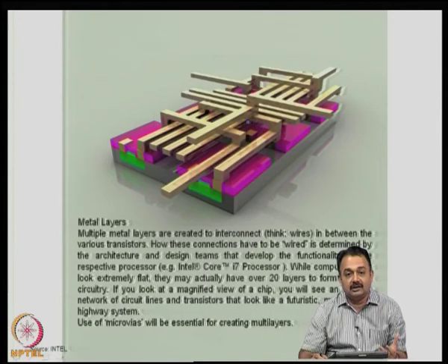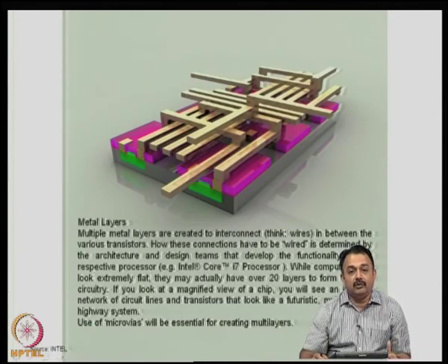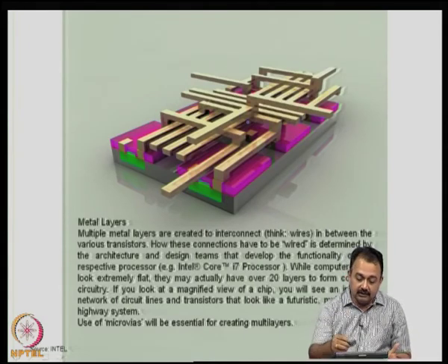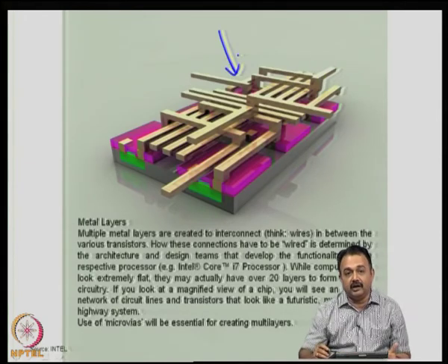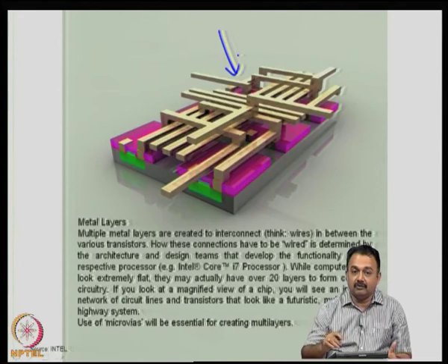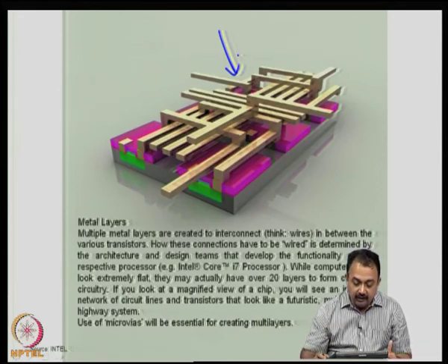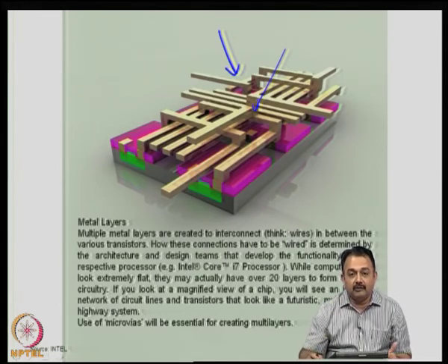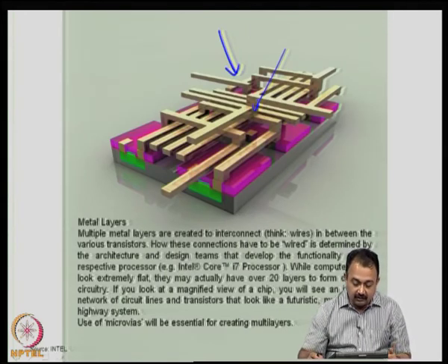Now that the basic transistors have been formed in the base layer, now we are going to interconnect between transistors using different layers. So, this picture here shows you how interconnect wires are formed to connect the various transistors below. So, this is also known as the wire. So, wiring density here is very important, and in this particular case, for example, the connections here are between various layers of copper interconnected by small vias. Micro vias are used to create established connection between various conductors.